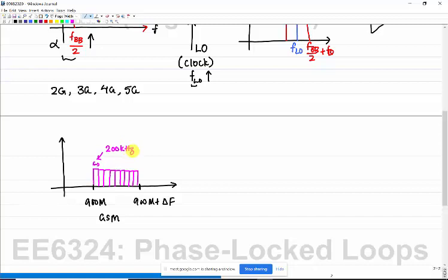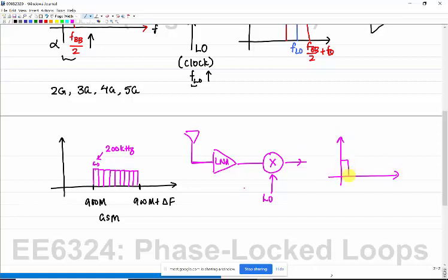Okay, so you have your wireless receiver in your phone, and you are 2 or 3 people, or let us say more people are there, and each one of you is able to talk. Just think about it. This signal is coming at your receiver antenna, and you will surely have a matching network and so on, with an LNA and everything. You have to down convert this signal using the local oscillator back to your baseband signal, which is where your information is located. This is what I need to do.